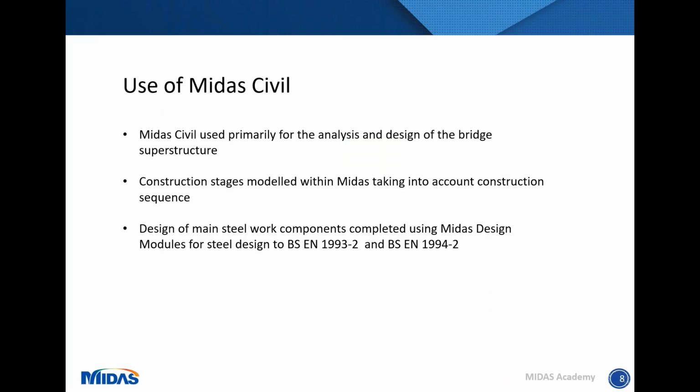I'm now going to start discussing how Midas was used on this project. Midas was mainly used for the analysis and design of the superstructure. The construction stages were modeled within Midas to take into account the construction sequence that we envisioned. Further to this, Midas was used primarily for the design of the main steelwork components, using the Midas design modules for steel design. This was mainly for the steel elements, so the bracing elements within the model, and the other module used was for the composite design, which deals mainly with BS EN 1994 Part 2.